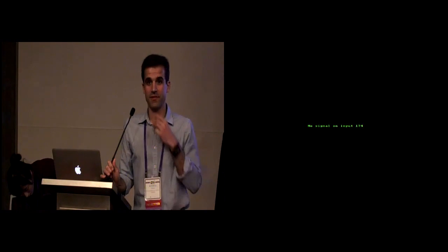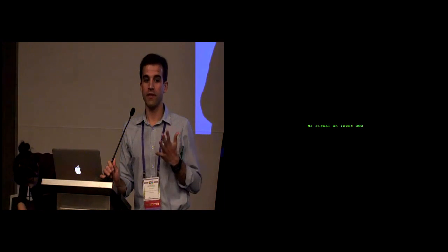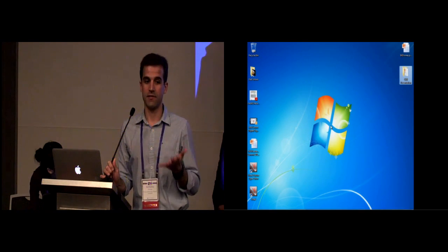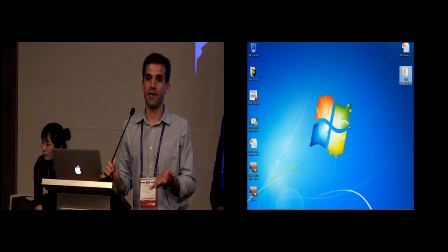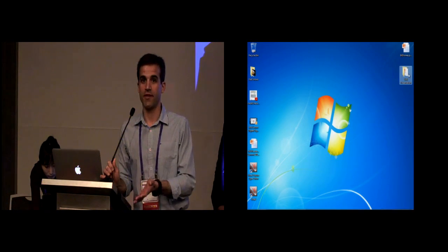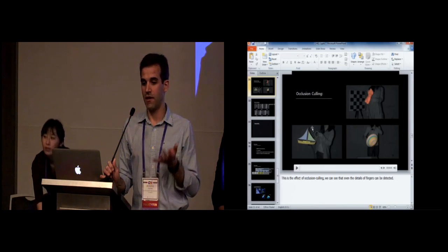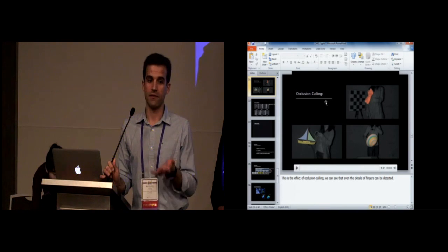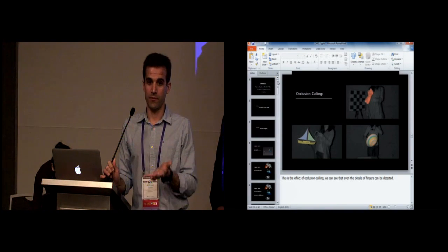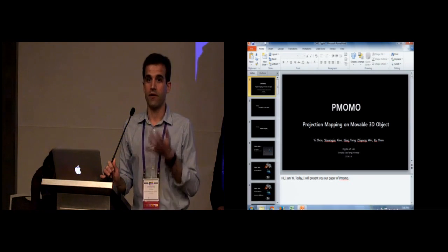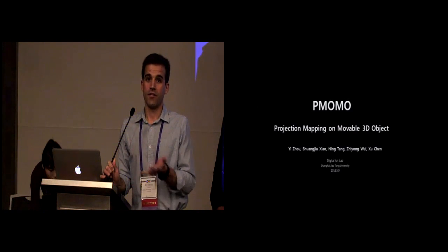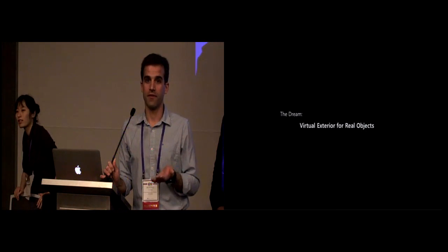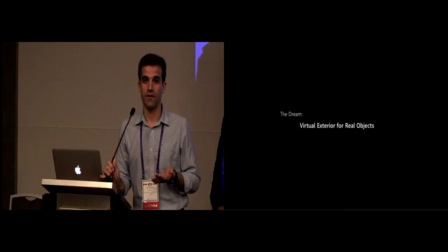I'll address that after. So no, and we're fairly limited in the number of augmentations that we can apply to the drones themselves. This is mainly because with miniaturization comes a compromise between weight to thrust ratio. So as we explore new geometries and as we try and miniaturize these drones, quadcopters may no longer be the most efficient way to do so, because we need a propeller clearance area around each structure, and the more weight we add, the larger this structure needs to be. So we did not explore audio, but that would be one of the drawbacks of having to add extraneous hardware.